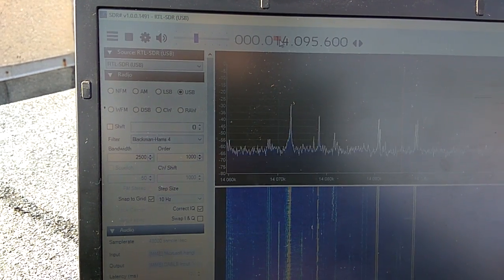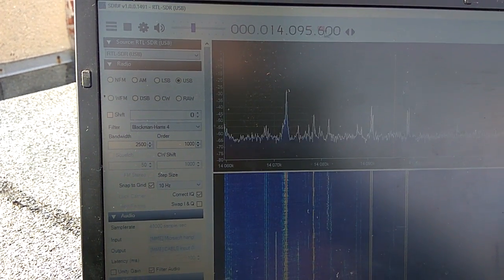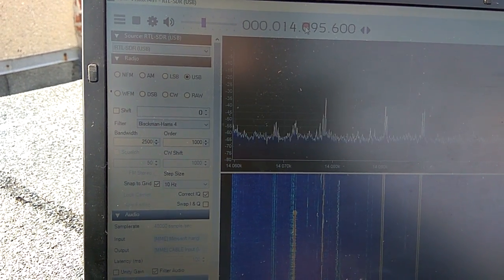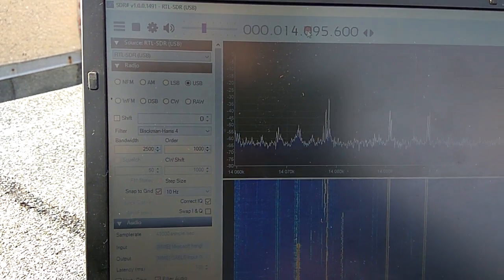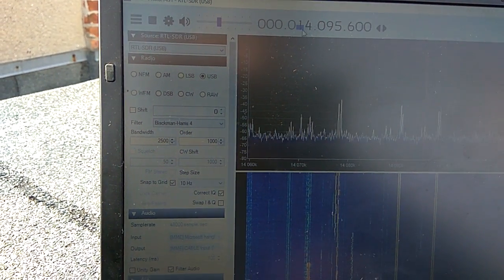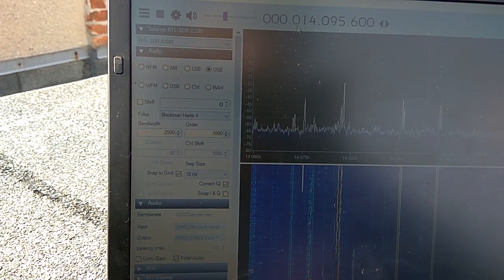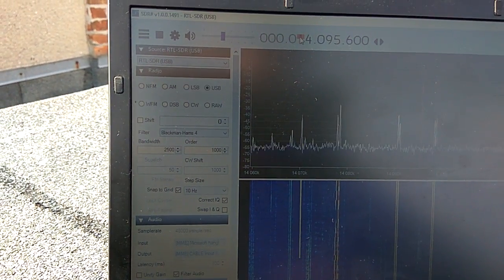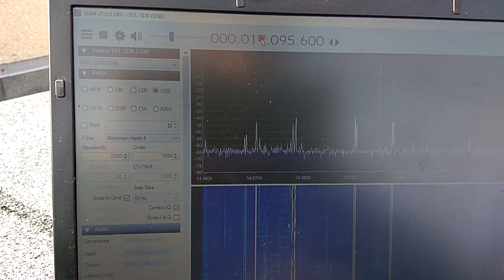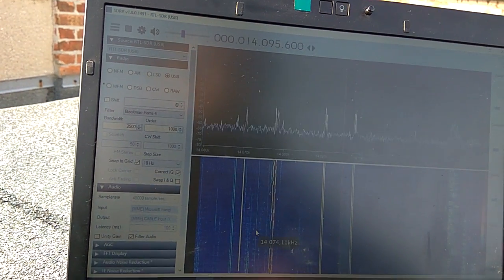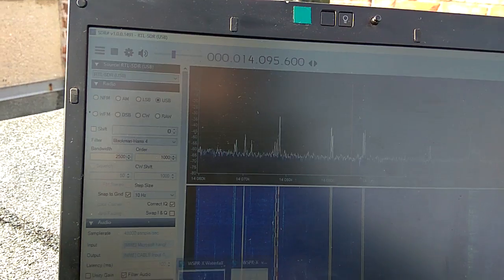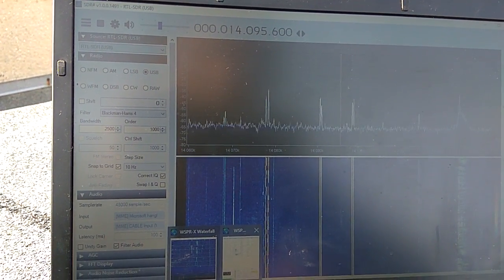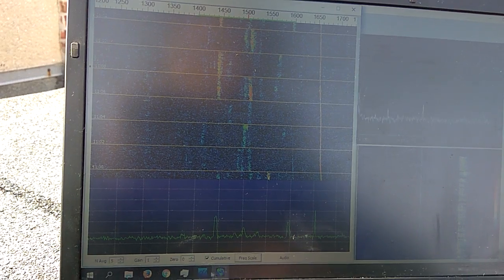It's really important because you have to look for the dial-in frequency, not the actual transmit frequency, because there is a 2.5 kilohertz offset between the two. That one is set for the 20 meter band right now. For more information you can Google up WSPR and you will find nice PDFs about setting it.